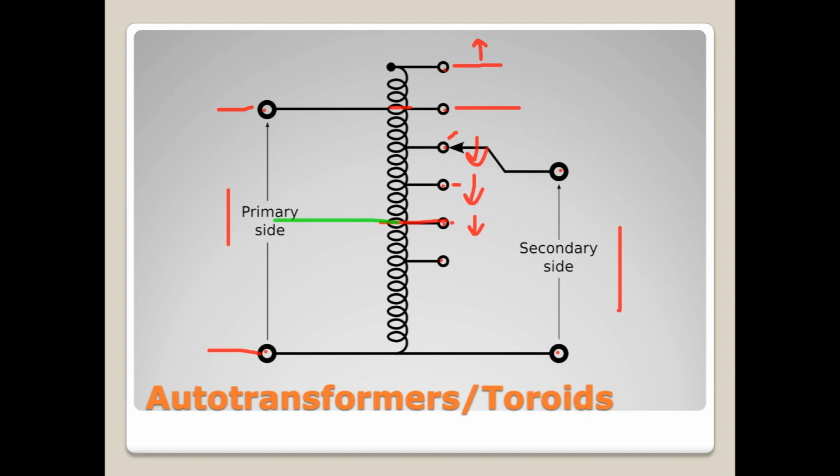That means that when I grab something from up here, this is now double the voltage, right? So it just depends on how it's all configured. We are essentially using this one coil as both the primary and secondary. Now, the reason this works, by the way, remember that we're not grabbing something that is just purely electrical, right? It is the same coil, but we've got the magnetic field involved here.